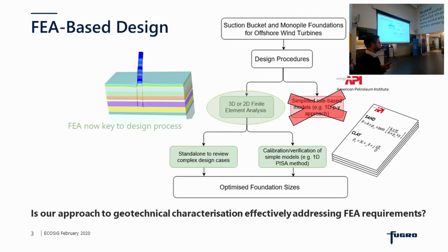Essentially, in terms of the renewables sector, we think about design for wind turbine foundations, we think about monopiles, we think about suction buckets, and to potentially a lesser extent in terms of use of FEA, we think about jacket piles. Now for monopiles, FEA has been much discussed recently via the outcomes of the PISA joint industry project, which obviously highlighted the benefits of using an FEA-based response.